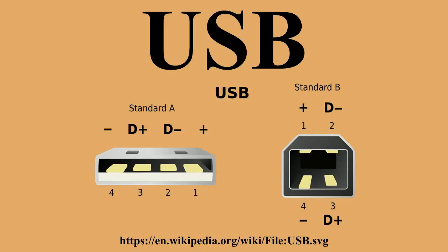Unlike other data buses, USB connections are directed, with both upstream and downstream ports emanating from a single host. This applies to electrical power, with only downstream-facing ports providing power. This topology was chosen to easily prevent electrical overloads and damaged equipment. Thus, USB cables have different ends, A and B, with different physical connectors for each.